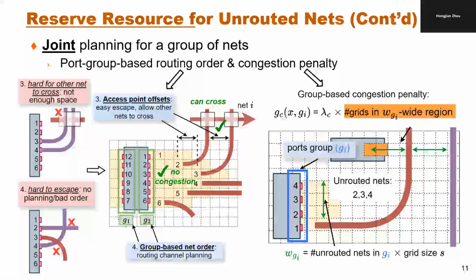Apart from the port, there are also conflicts between waveguides, especially for components with high port density. Without carefully planning the routing waveguide, we will easily block other nets. The waveguides that connect to those ports are usually close to each other. When some other waveguides have to cross this waveguide, there will not be enough space for putting two crossings consecutively. Observing that the waveguide space is usually defined by the final access port, we set some offsets among these ports so as to support consecutive crossing insertion.